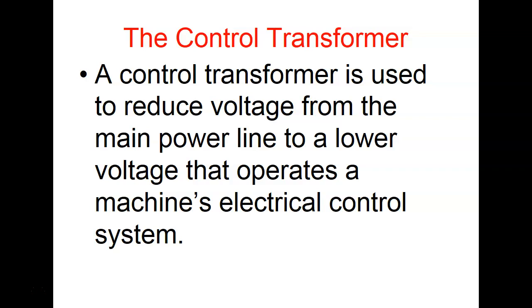And this is why Alabama Power wants you to have a really large power factor, moving toward 100%, because all their transformers and all their conductors have to handle apparent power. And what did I say they charge? They charge if you don't have a power factor over 95%. If you have a power factor of less than 95%, you're going to pay a penalty in your industry, not at your house. Alabama Power takes care of the power factor at your house, right? So understand that. But big companies have to manage their power factor.